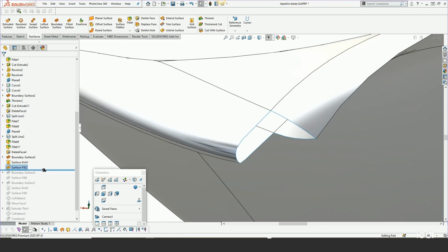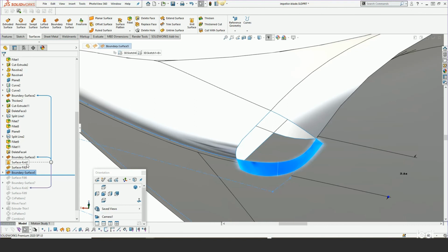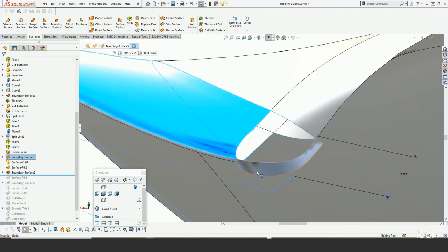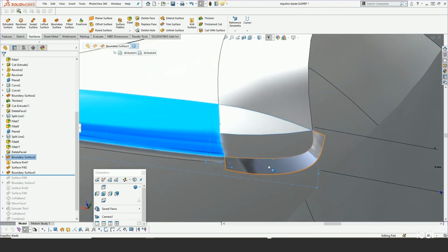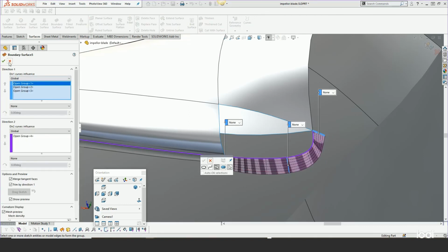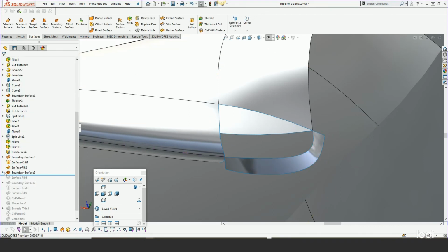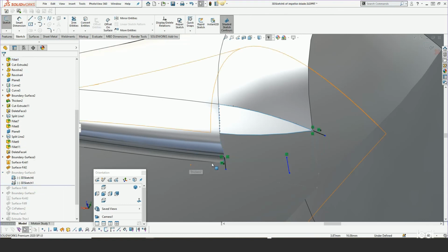So before I do that though, I'm going to create a reference surface. And if you look at my models, you'll see a lot of these reference surfaces. And they're all basically the same. And what they are is, if we edit into it, I've basically created a 3D sketch of some simple lines that are tangent matched to the existing model edges.